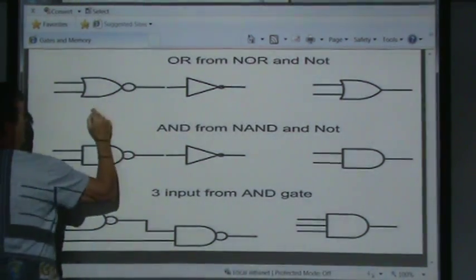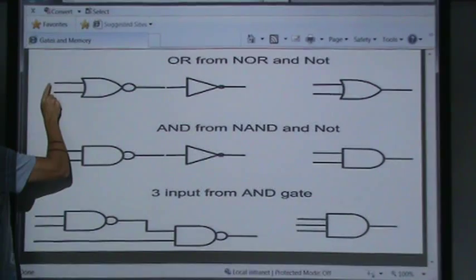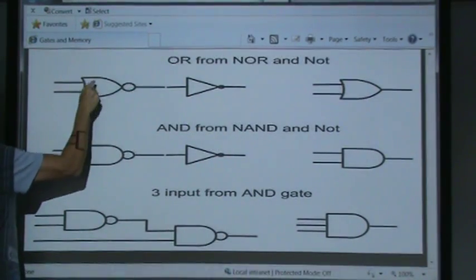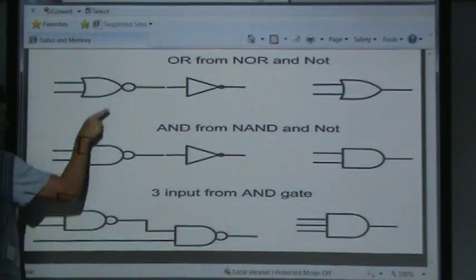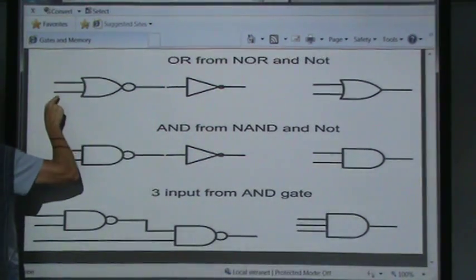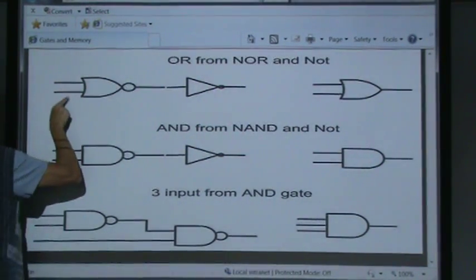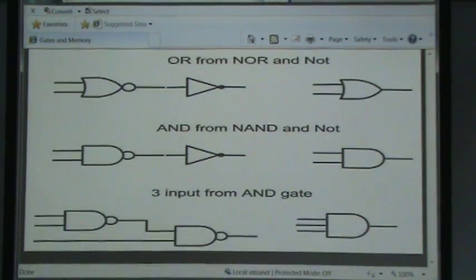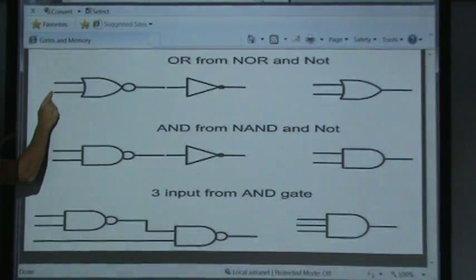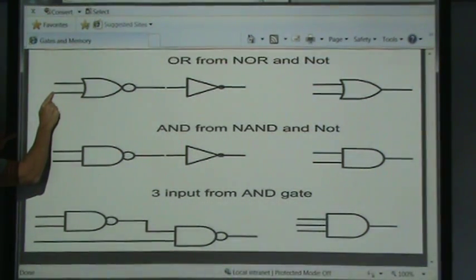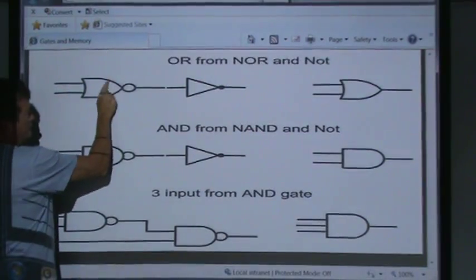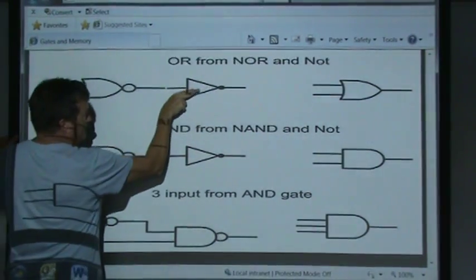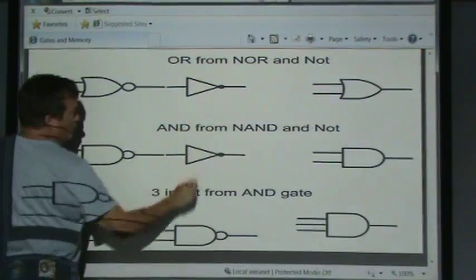This gate alone, we were saying if both of these were on, then the electricity could flow down to the bottom. This would be off. Now we're saying if both of these are on, then we'll flip this and turn it into being off. So for example, if this is a 0 and this is a 0, then the output of this will be a 1, which will make the output after it flips to the other side go back to 0.